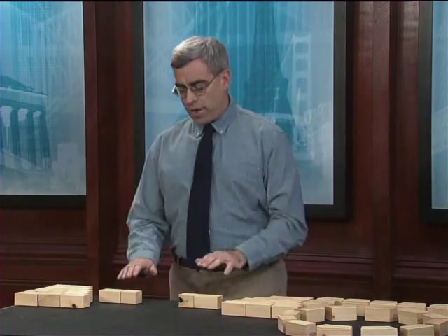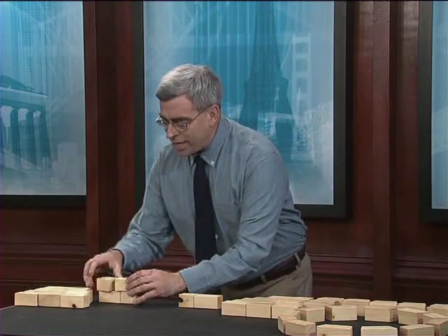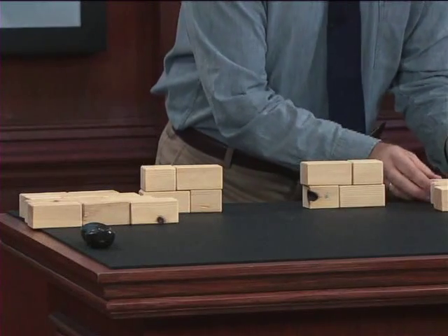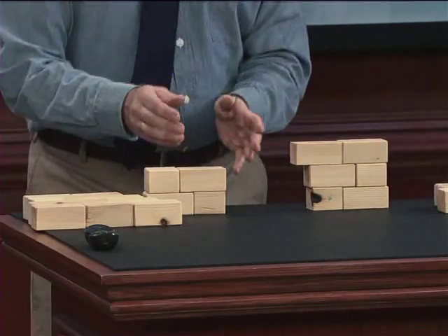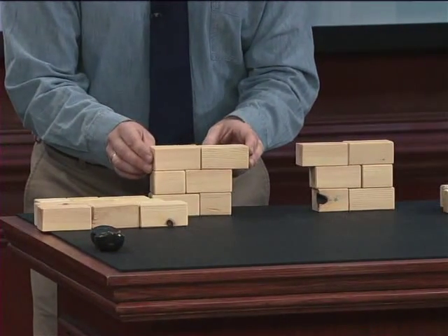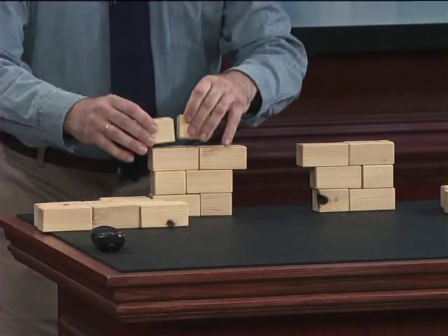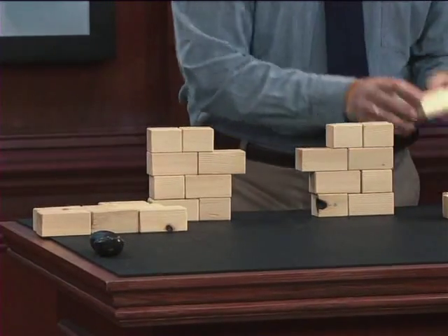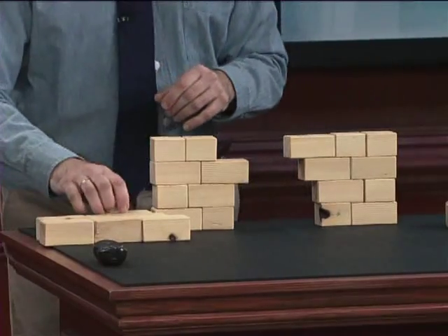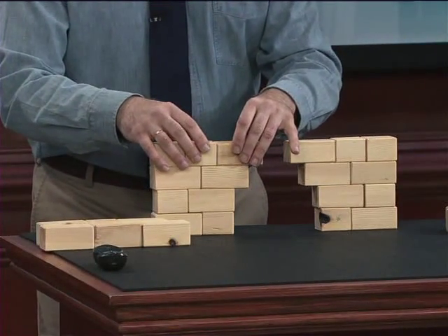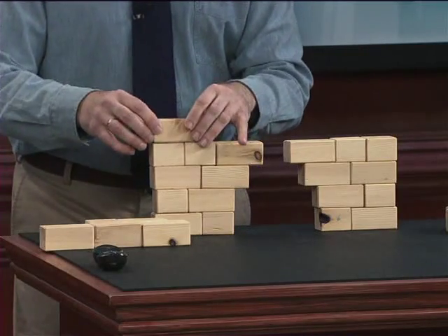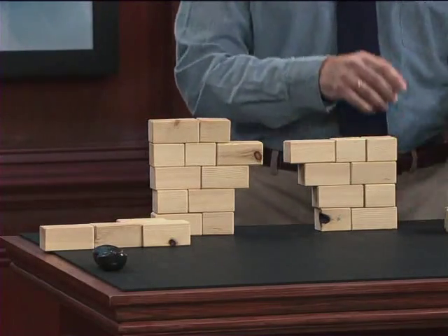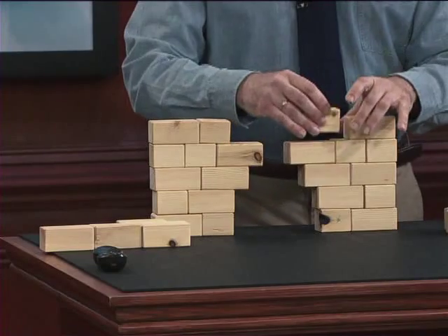Here's the opening that we're going to create. Here's my first course of stone. And now we're going to add successive courses of stone on top of that. Here's our first. Then above that, notice that the next course of stone is going to extend inward a little bit to start the process of closing the gap between the two different constructions that ultimately will form the sides of our corbelled arch. We're going to extend the third course in yet again. And now we'll add another course on top of that. And by the way, when I use the word course, I'm referring to layers of masonry. It's the technical term that's used in reference to masonry construction.